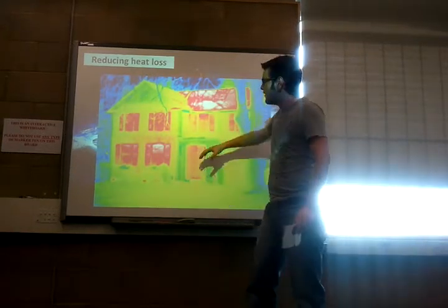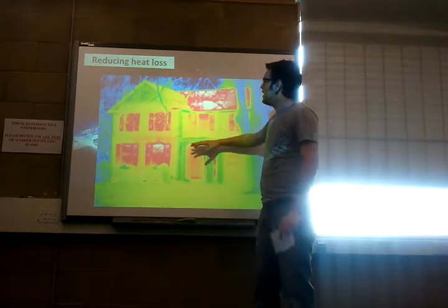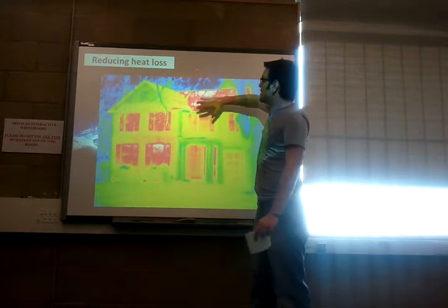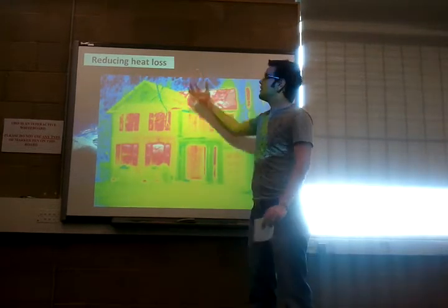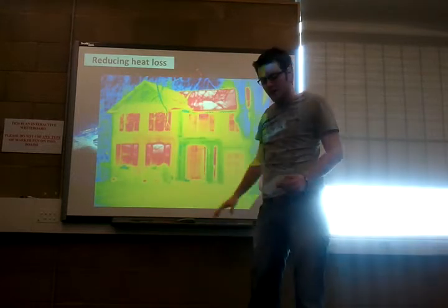With convection, if you've got any spaces in between your windows or in your doors, cold air can come in, and the heat will be rising up. If there's no insulation at the top, then the heat will rise straight out the top of your house, the same as it will go out the top floors, out the windows.